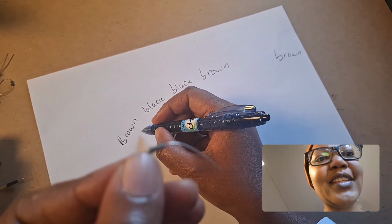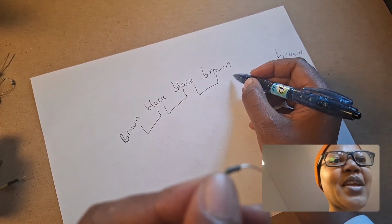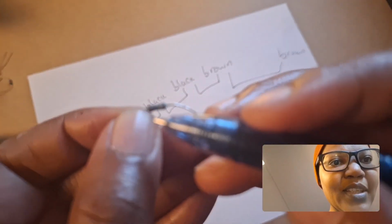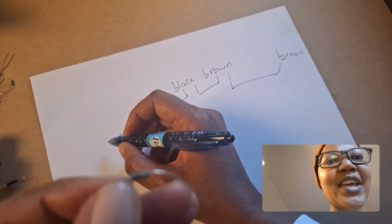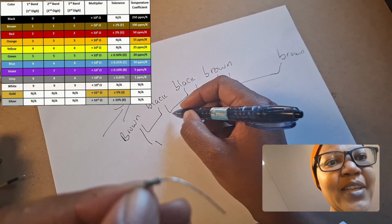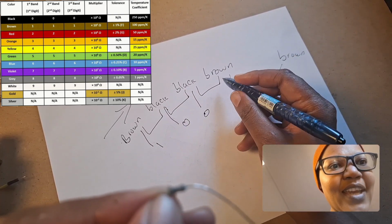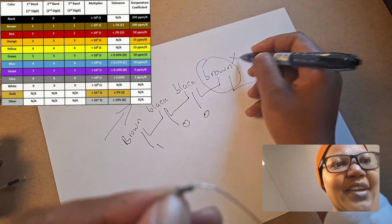The distance between this and this is the same, but the distance between this brown and this brown is longer. So hence we are going to calculate from this side. The value of brown is 1, the value of black is 0, 0, and this becomes our multiplier.